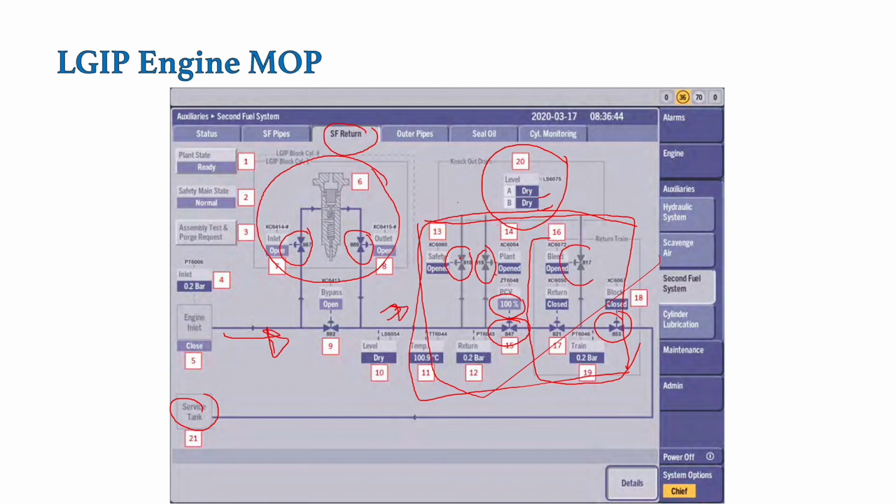And this valve, as you can see, is also vented to the atmosphere, but this valve is opened when the system has fully stopped. Basically this valve and this valve will be closed and this valve will be opened. So this system is basically called the block and bleed system. So this valve will be opened, so this basically will fully isolate the supply system from the main engine.